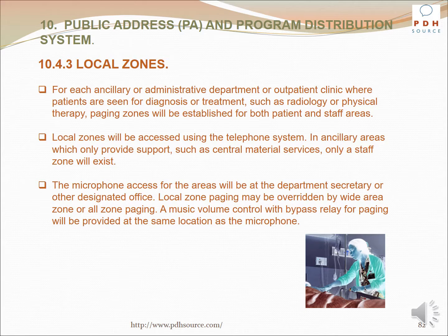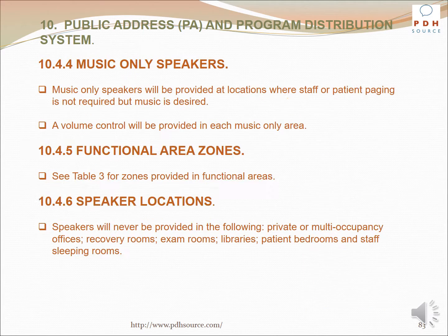Local zone paging may be overridden by wide area zone or all zone paging. A music volume control with bypass relay for paging will be provided at the same location as the microphone. Music-only speakers will be provided at locations where staff or patient paging is not required but music is desired. A volume control will be provided in each music-only area. See Table 3 for zones provided in functional areas.